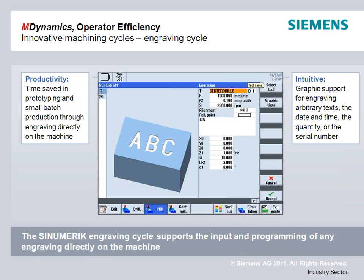We also have engraving cycles built in. So even if you need to do something like putting a serial number on each one of your parts, or if you need to mill in the word prototype or some other model number that you need, these are available where the operator can do these just standing there at the machine, type them in, no CAM system involved.